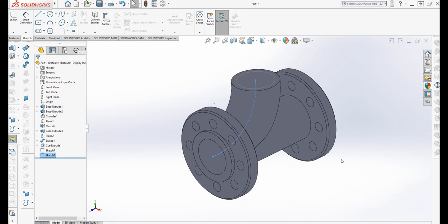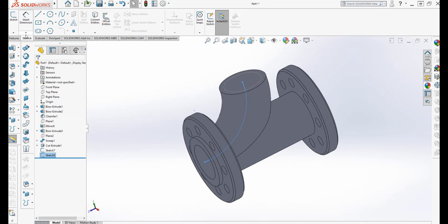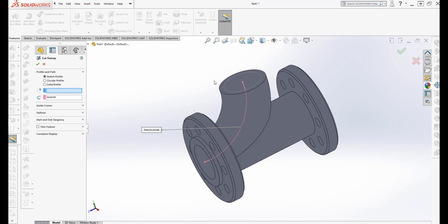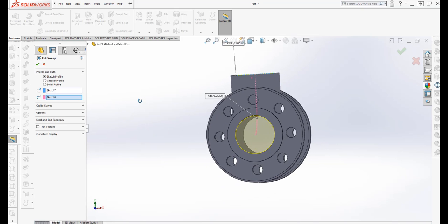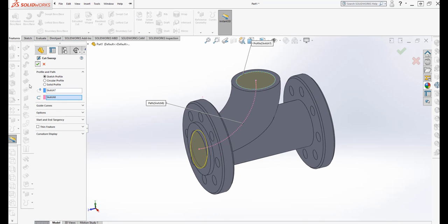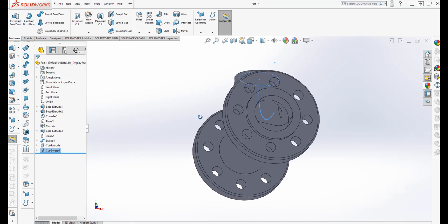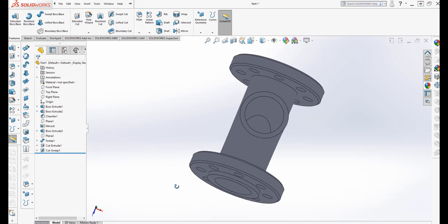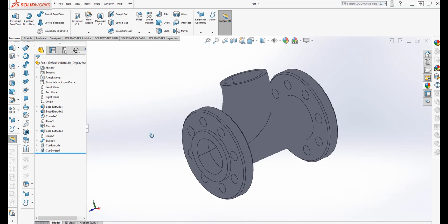Let's get out of the drawing and select the profiles, and then the sweep. I used the extrude sweep a while ago. It was sweep boss. Now I'll use the sweep cut. So let's do a sweep cut, and then it automatically reads it. See that it will cut it now. There is a hole right there. Now it's better.